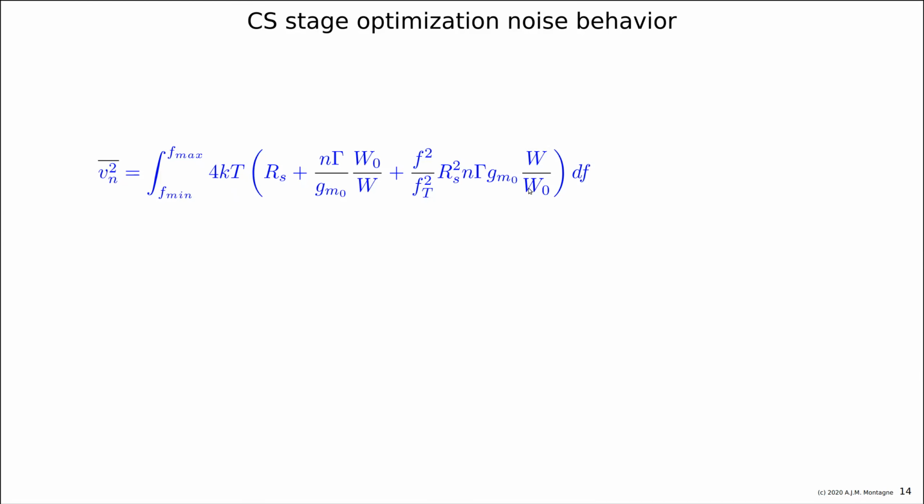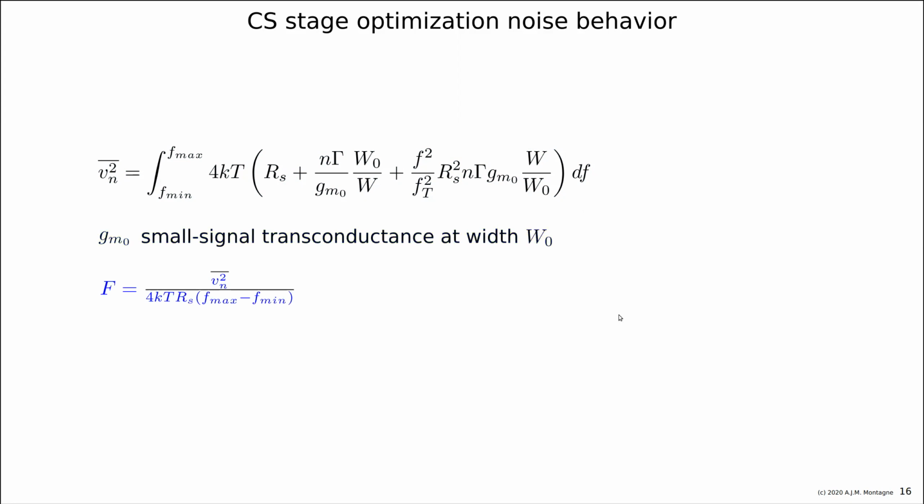And with that width, we could calculate the noise factor, the total noise, and then we have the showstopper value for this frequency range in the process. So you find this one. The definition of the noise figure is, of course, the total source referred noise divided by the noise that is only coming from the original signal source.